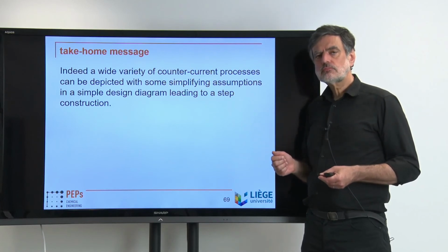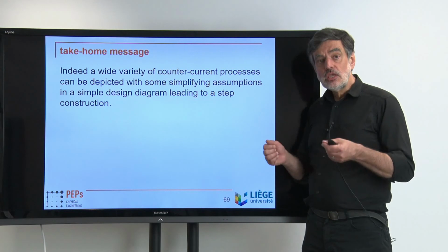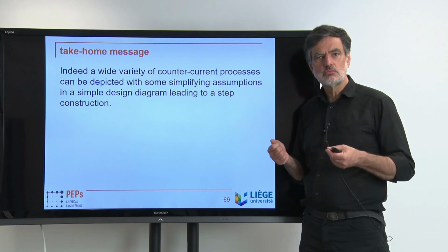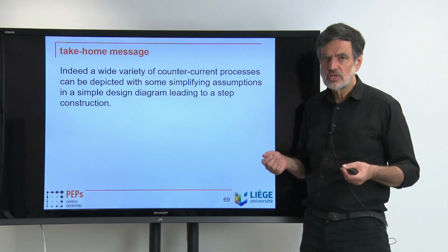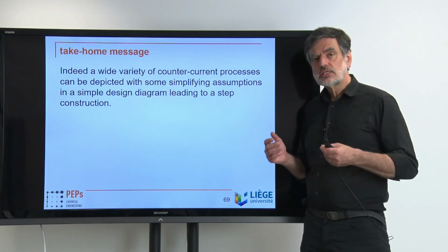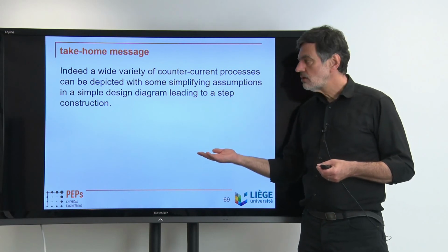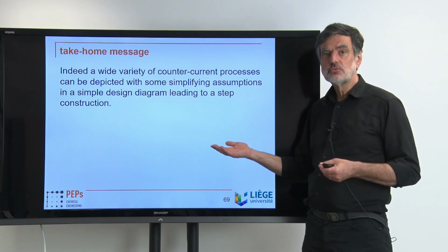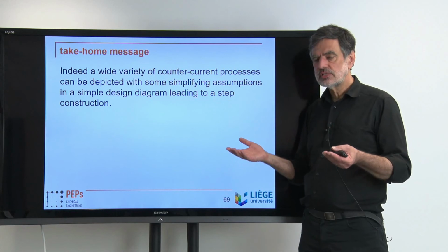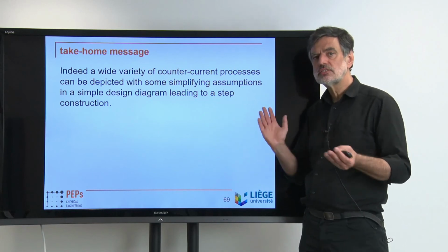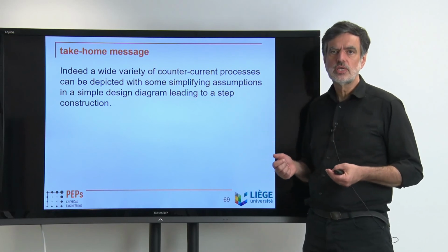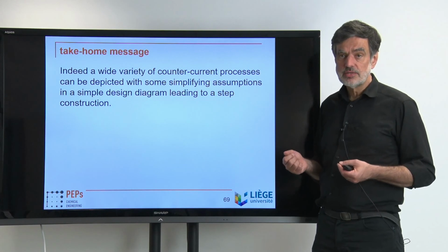As I said in the introduction, many videos ago, even if you do the simulation with a corresponding simulation tool, Aspen or ChemCAD or whatever, not advertising any, in that case you typically also want to depict your result in such a diagram, possibly if convergence fails, to see what's actually happening, or if convergence works but you get strange results, you plot it and directly see what happens in such a diagram. And that's why these diagrams are so valuable, even if you are doing the design by a simulation.